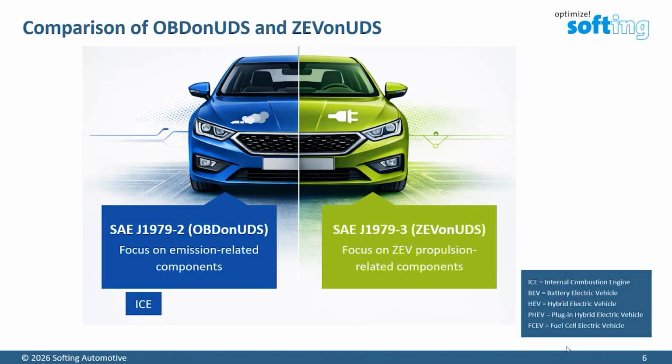The biggest group is internal combustion engines, followed by plug-in hybrid electric vehicles. They can be charged from the outside, but inside they also have a combustion engine, which must comply to OBD on UDS. And the same thing applies for hybrid electric vehicles. They cannot be charged from the outside. They have a smaller battery which can be charged by the combustion engine, but for homologation, the combustion engine part is important, so it must comply with J1979-2.